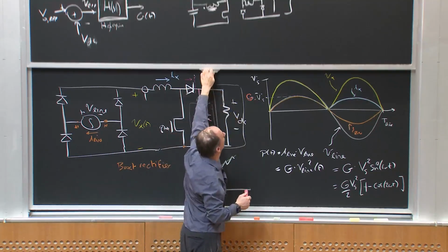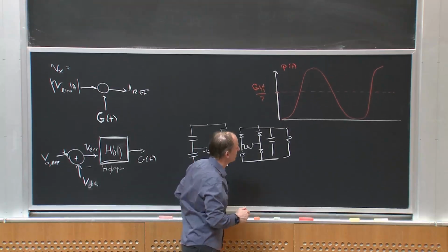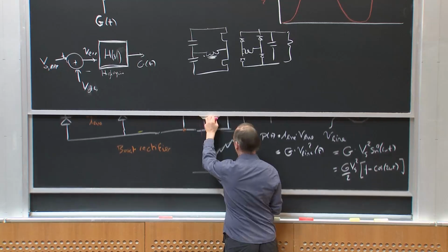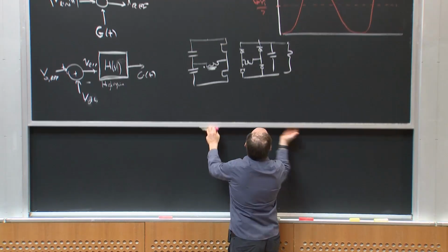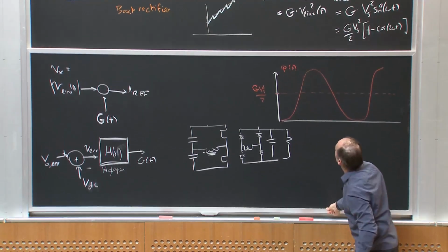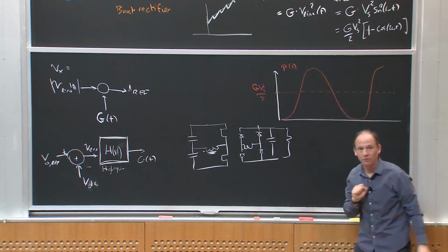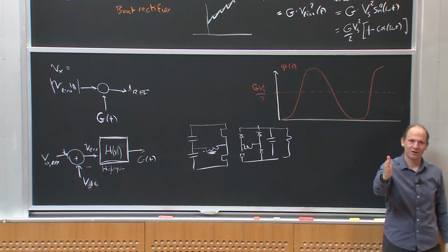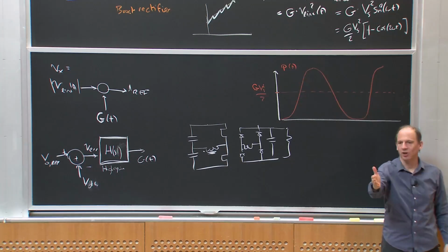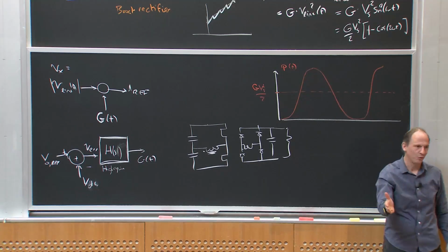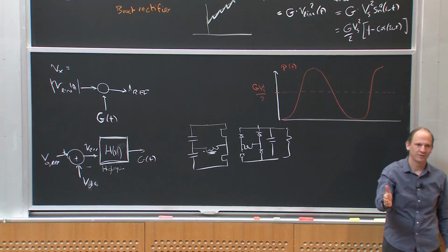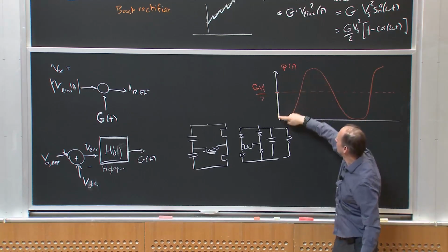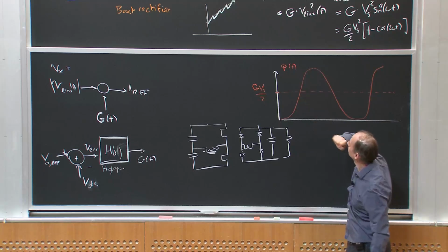So basically every half cycle, both the line current and the line voltage go back to zero. And when the line current and the line voltage are zero, there's no power coming from the line. In fact, it doesn't matter what current I want to draw from the line. If there's no line voltage, I can't get any current, I can't get any power out of it, right? So that's why I have this sort of square law power versus time, okay?